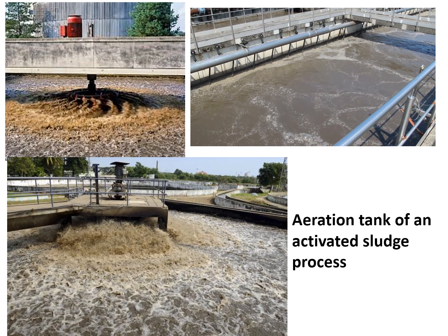Next is your activated sludge process, or aeration tank. It's a biological treatment process. Here an active mass of microorganisms is kept, and here you can see the aerators. These aerators are constantly supplying air and oxygen to the microorganisms, and these microorganisms use organic matter as their food and degrade it, and they are responsible for the degradation of organic matter. So it's a purely biological process.